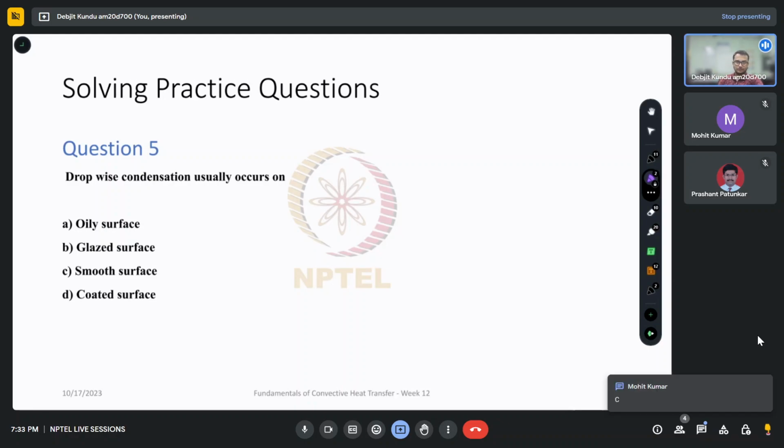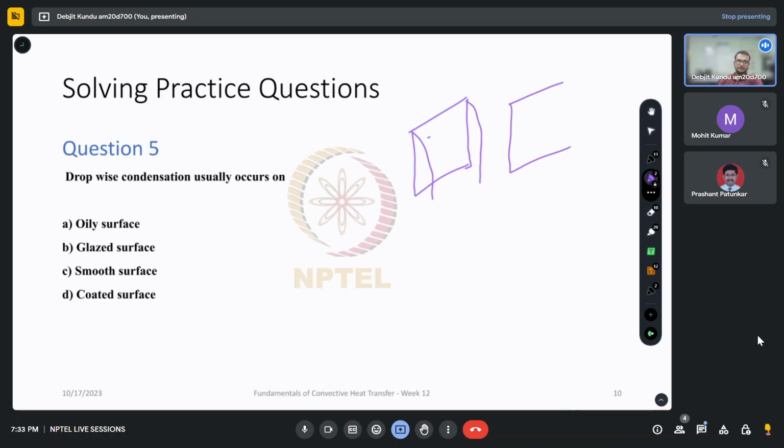So first of all, what is dropwise condensation? If we have a wall which is cooler than the ambient fluid around it, then that ambient fluid will condense on it. So another alternative of dropwise condensation is film condensation, in which an entire, continuous film of liquid is formed, and that goes down due to gravity like this. And the other option is it can condense in a dropwise manner, in which liquid drops would form like this, and these drops would now roll down due to gravity.